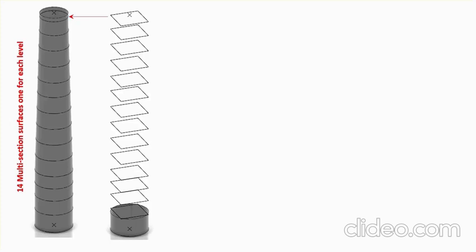And my strategy for doing it is creating these 14 planes. On them, draw circles of the appropriate diameter, and then do a multi-section surface to create the structure. The very top level is just the extrusion that is done by 600 millimeter at the very end. Don't worry about these points that you see at the very top and the bottom. We're gonna take care of those later on. Those are basically the places that we're gonna apply coupling and apply the boundary condition and things like that at those points. Don't worry about it.